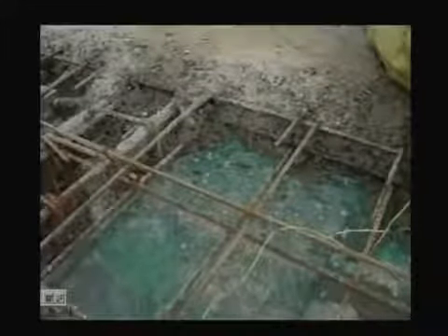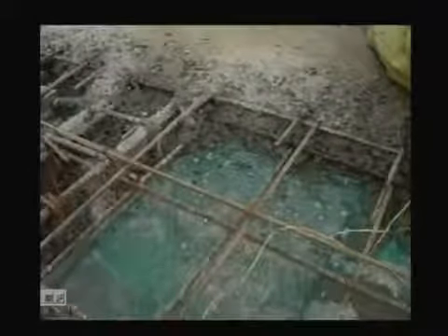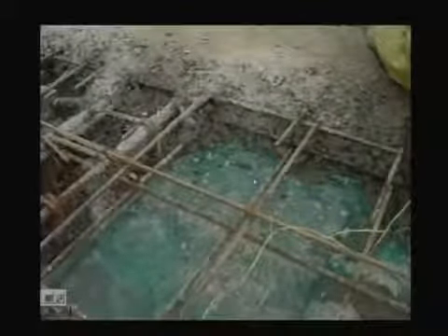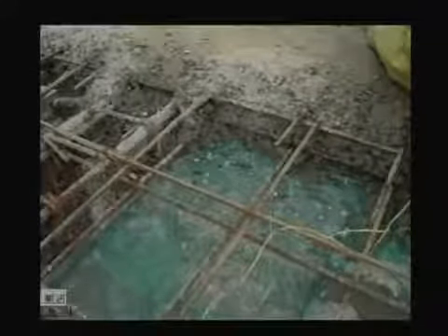Considering this particular reinforced concrete element, this is nothing but the slab element. Here we have concrete, and we have bars in 2 directions, at the top and also at the bottom. For these bars you have to specify the dimension: what should be the dimension of the bars, what is the spacing of these bars, and what should be the depth of the concrete?